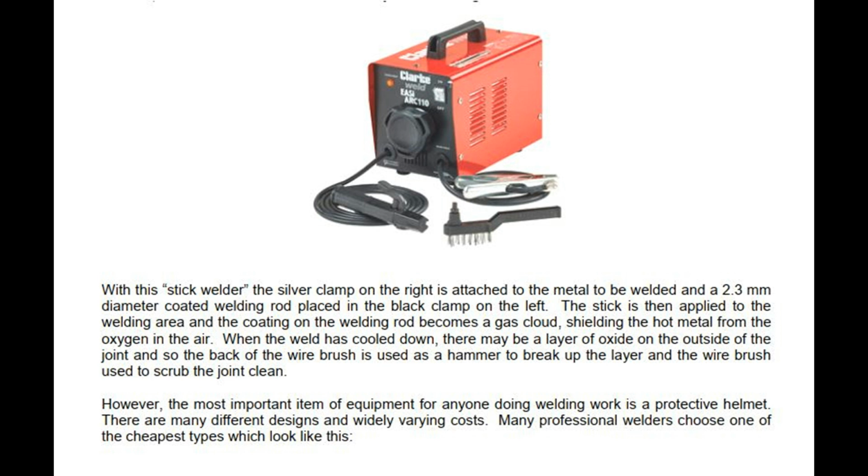When the weld has cooled down, there may be a layer of oxide on the outside of the joint, and so the back of the wire brush is used as a hammer to break up the layer, and the wire brush used to scrub the joint clean.